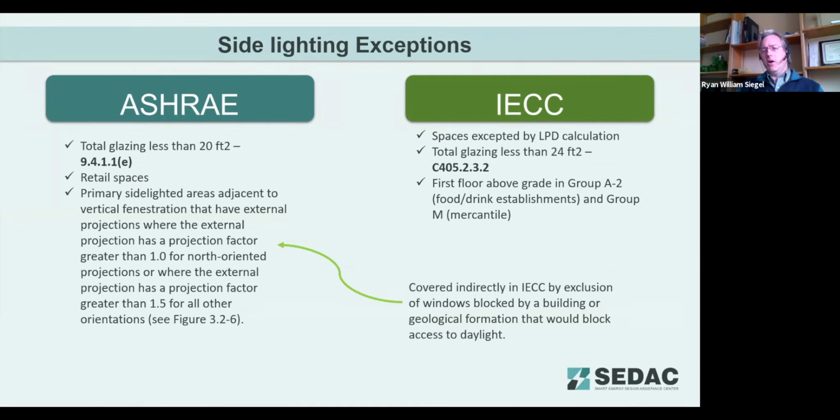That may help from an HVAC perspective, having that projection out there to shield those windows from sunlight, particularly in the summer, but you're trading that off, and it may preclude some daylight harvesting controls from being used. I don't want to necessarily guess which trade-off is going to be better, the mechanical benefit versus not being able to harvest that daylighting, but I'm probably thinking mechanical might win on that one.